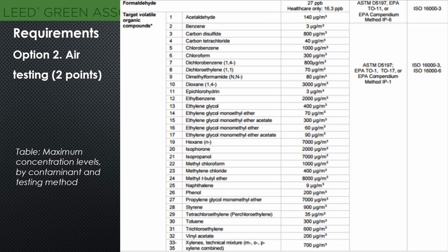So we need to conduct all the measurements before occupancy, but during normal occupied hours, with the building ventilation system started at the normal daily start time and operated at the minimum outdoor airflow rate for the occupied mode throughout the test. For each sampling point where the concentration exceeds the limit, take corrective actions and retest for the non-compliant contaminants at the same sampling point, and repeat until all requirements are met.